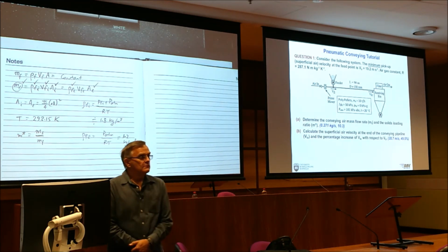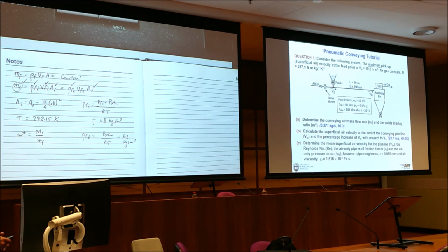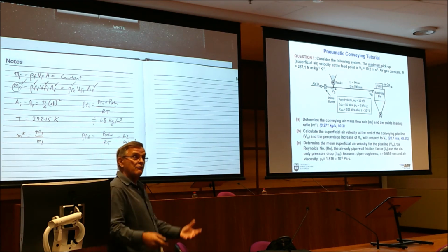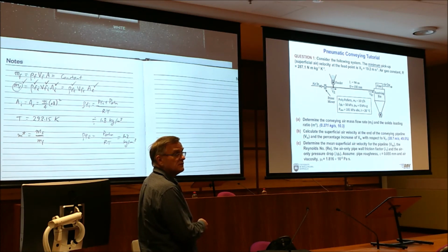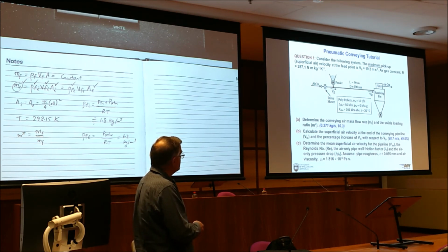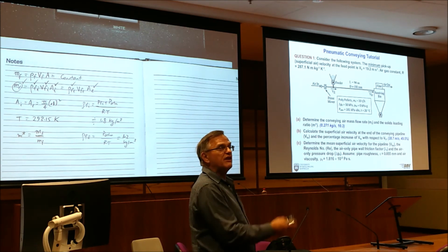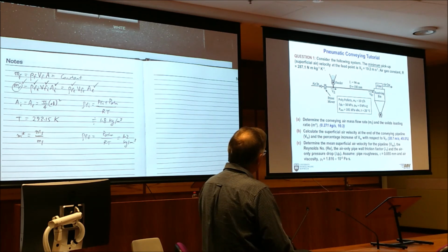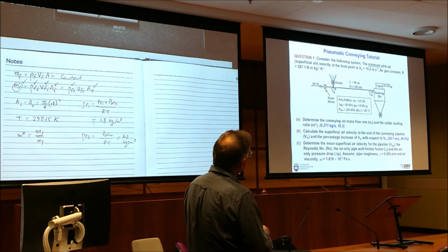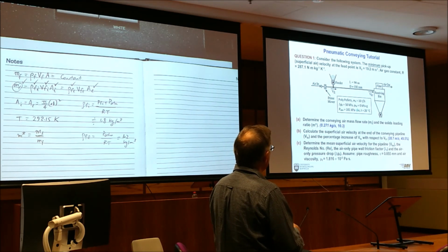The rest of this is simple calculation. I don't think we need to spend any more time unless you've got a concern. The third question is using your Moody diagram. But before you do, to work out your air-only losses, we're going to calculate your pressure loss of air, delta PF, using the equation I showed you before. So to do that, we need to get our friction factor, lambda F, which we get from Moody. To do that, we need Reynolds number. But to do that, we work with our mean conditions. So you firstly need to calculate the mean superficial air velocity for the pipeline. So for that pipeline, what's the mean superficial air velocity? How would you calculate that?